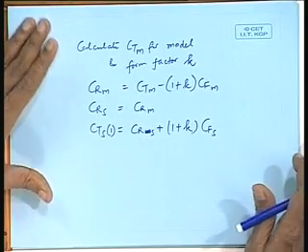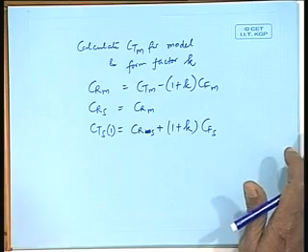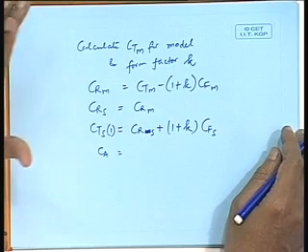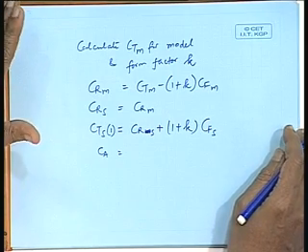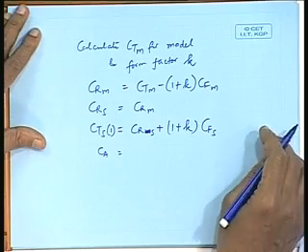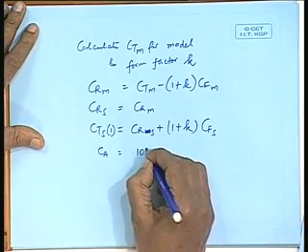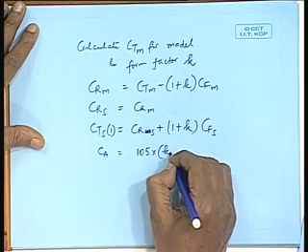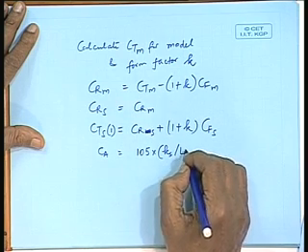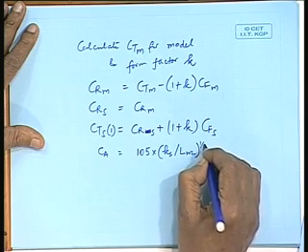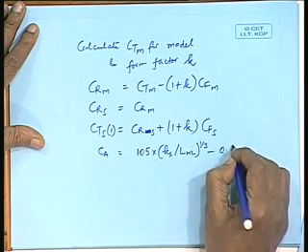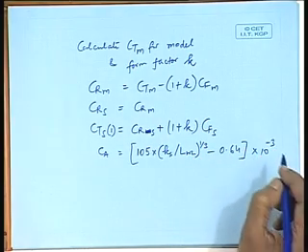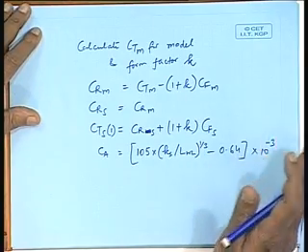Now, we have said that there will be a correlation allowance, that is CA. I told you yesterday that ITTC has given a length dependent CA value, and that formulation is like this: 105 into (Ks divided by length LWL) to the power 1/3 minus 0.64, into 10 to the power minus 3, where Ks is the roughness of the surface.